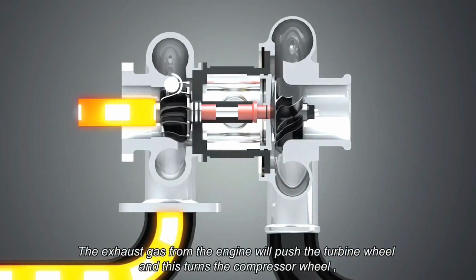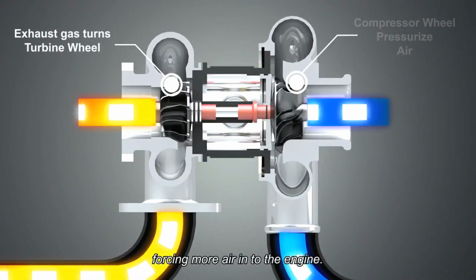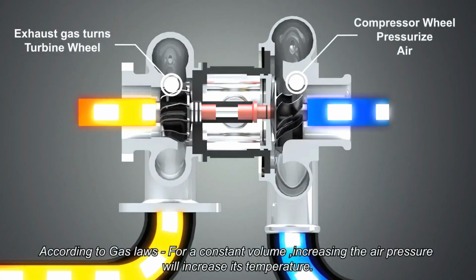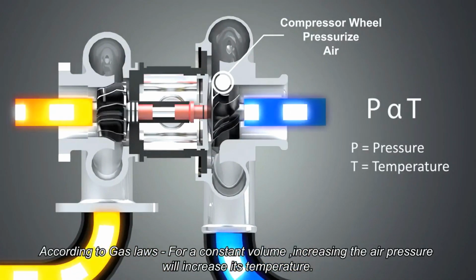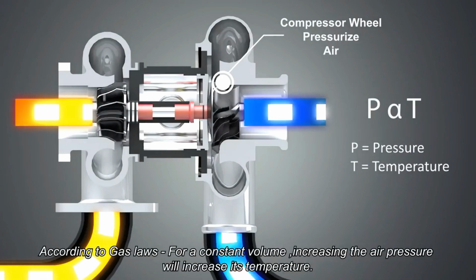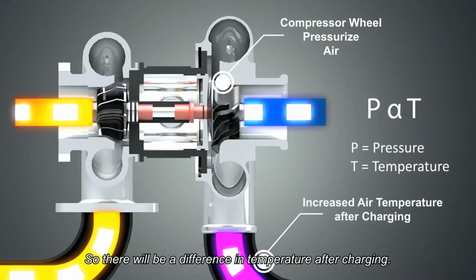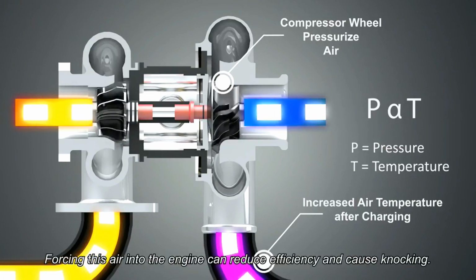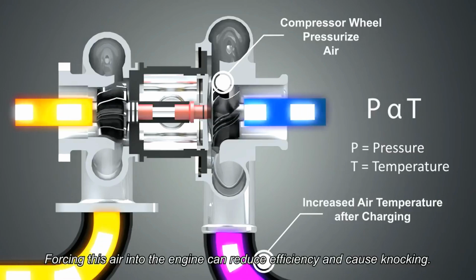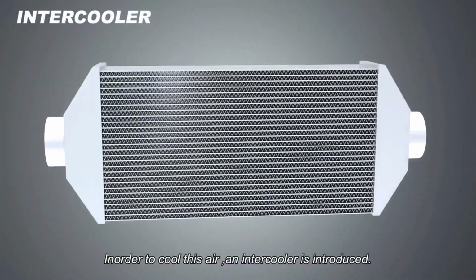The exhaust gas from the engine will push the turbine wheel, and this turns the compressor wheel, forcing more air into the engine. According to gas laws, for a constant volume, increasing the air pressure will increase its temperature. So there will be a difference in temperature after charging. Forcing this air into the engine can reduce efficiency and cause knocking. In order to cool this air, an intercooler is introduced.